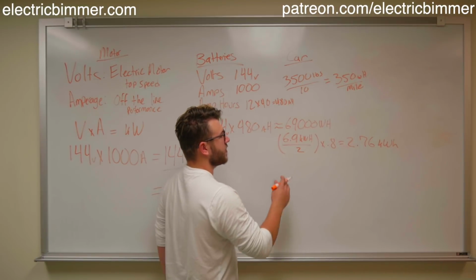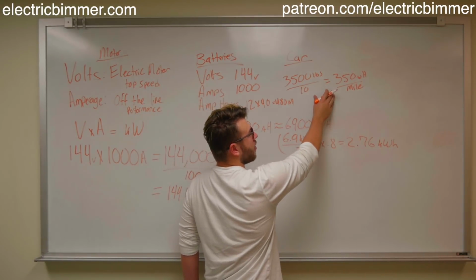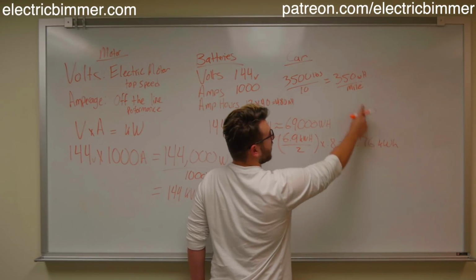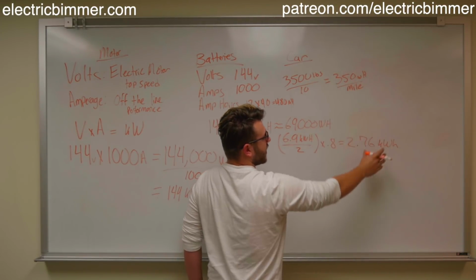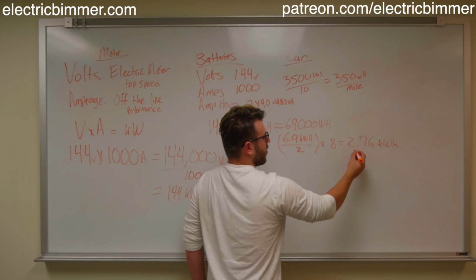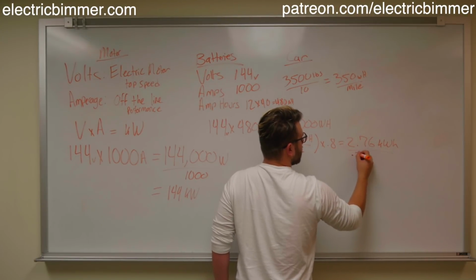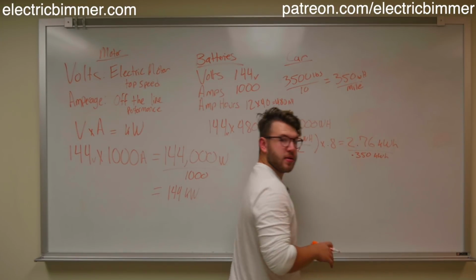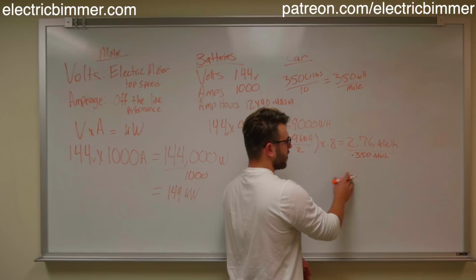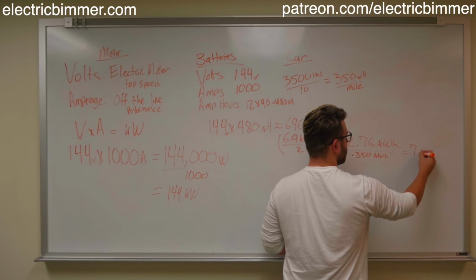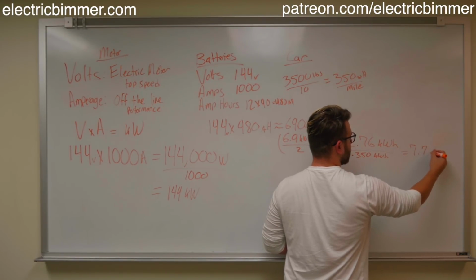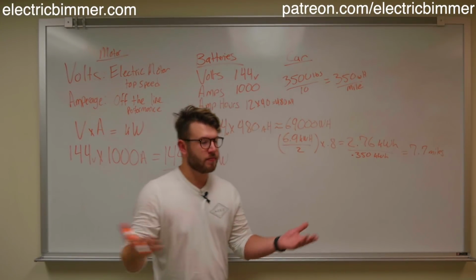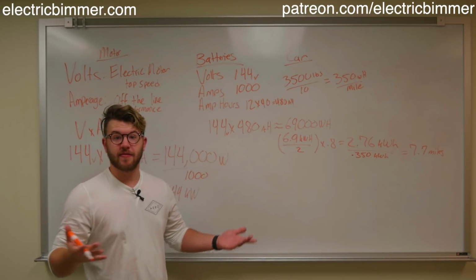And again, we'll do the same thing where we divide it by our car estimation, but remember, this is watts per mile, this is kilowatts. So we have to divide this by 1,000, and then we can divide these two together. So we're going to divide this by 0.350 kilowatt. So with this battery pack and my car, we're going to get about 7.7-ish miles. So not very far, but for my usage of testing, that's going to be fine.